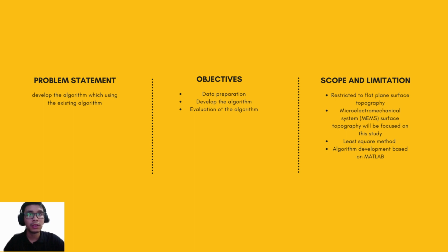The objectives of the study are data preparation of the surface topography measurement taken using a non-instrumental method such as digital imaging and of simulated topography data of a micro electromechanical system, and to develop the algorithm using existing techniques that can automatically identify and select the region of the surface that we are interested in and make it more suitable for use as a reference plane in computing and subtracting the least square mean plane.